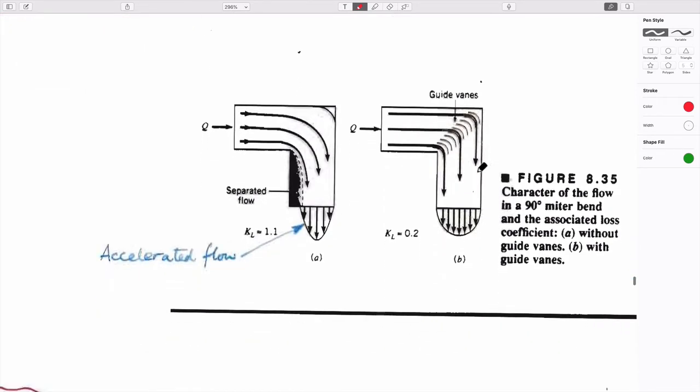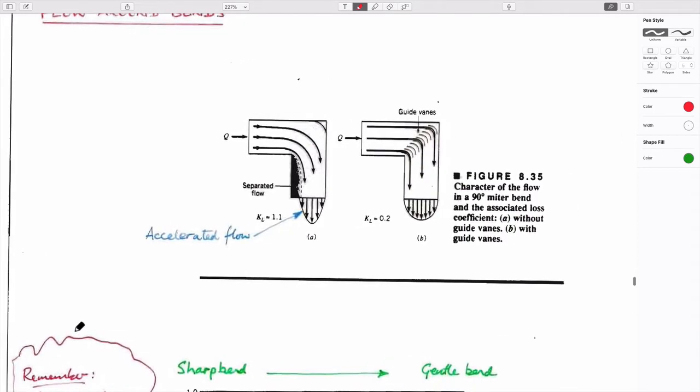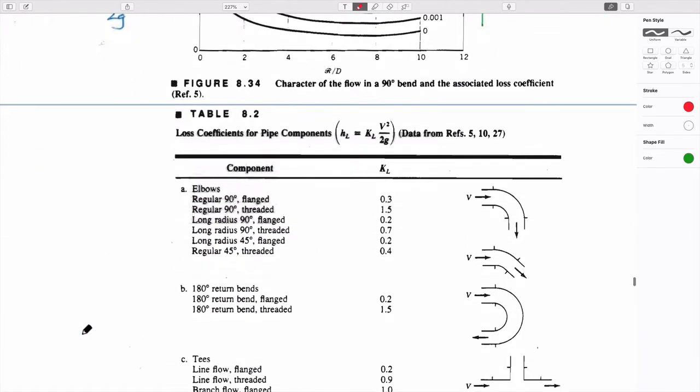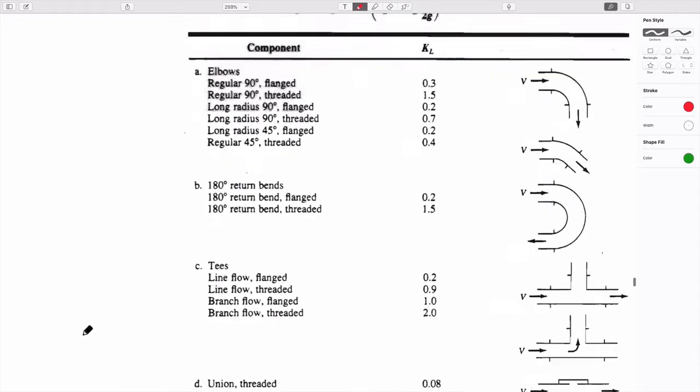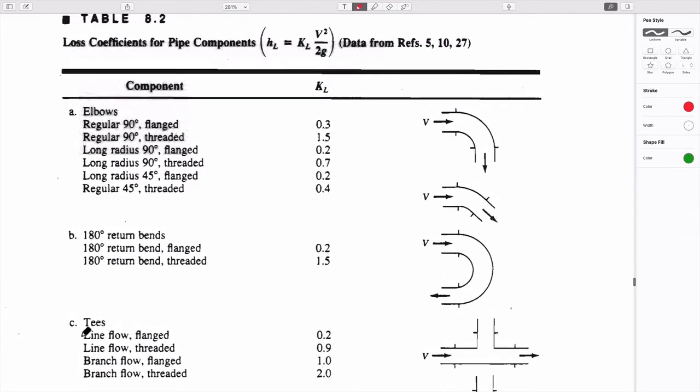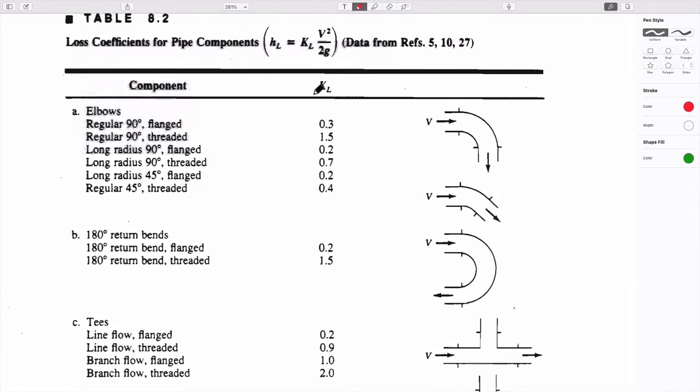And other behaviors in fittings, which are defined in terms, again, of the shape of the fitting, even going around a bend in a system. And so there are many tables that give you values for what those should be. They should all make sense. They're all defined in terms of a single loss coefficient. They're constant, which requires that we're assuming that the flow is turbulent. And they vary depending on whether they're flanged.